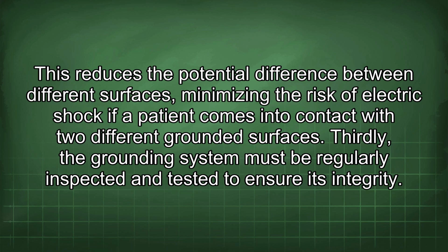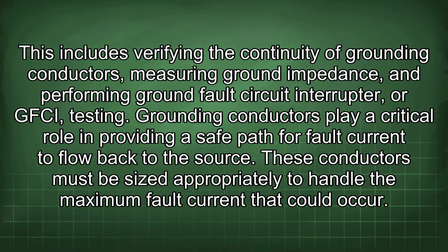Thirdly, the grounding system must be regularly inspected and tested to ensure its integrity. This includes verifying the continuity of grounding conductors, measuring ground impedance, and performing ground fault circuit interrupter, or GFCI, testing.